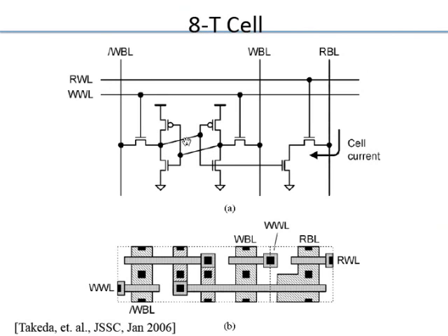What if you want to read this left-sided transistor? Let's look at if it's 0 here and 1 here. So if it's 0 here, this is off, so this remains at 1. Whereas if this is 1 here and 0 here, this 1 turns it on and discharges it. Discharge only happens through here. Remember, when we do a read, the write word line is kept 0. So we don't access the internals of the cell at all during a read.